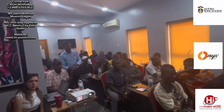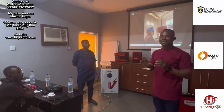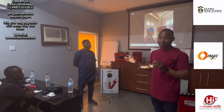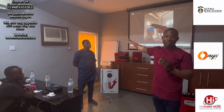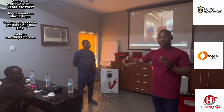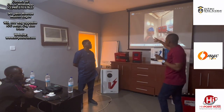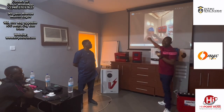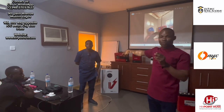Yeah, raise up your hand. You want to talk? What was done here is that all the batteries were connected in series and parallel. For that battery system, this is a 48 volt system, so you series 4 and you parallel. Then all the battery inlets come to the bus bar. From the bus bar, we feed our inverter. The inverters were also connected, do you understand?